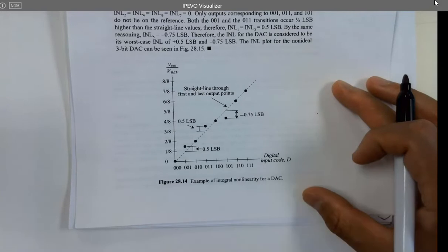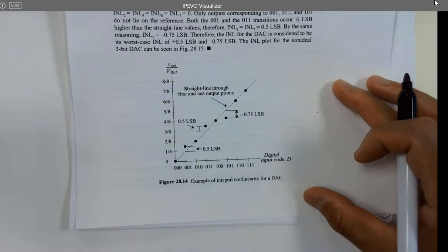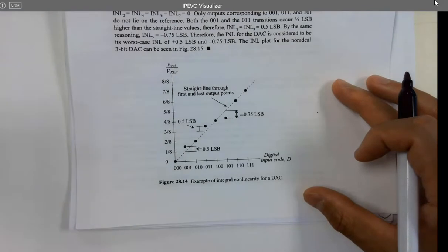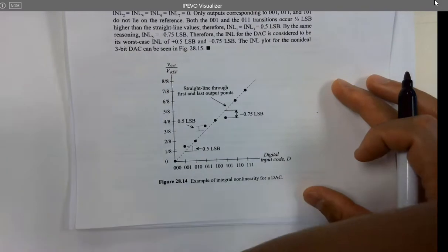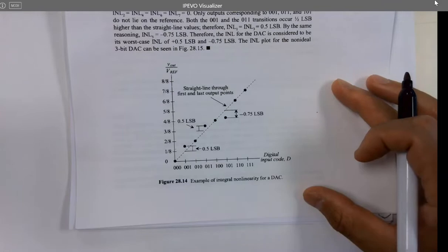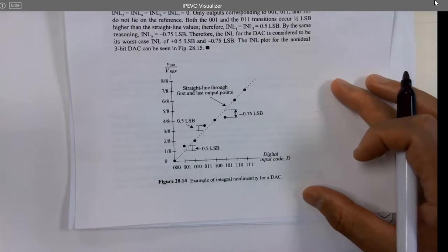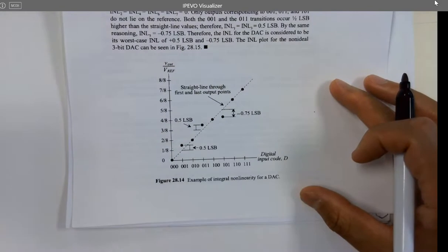So you have one LSB as a digital one. It has a corresponding 1-bit increment in the analog. The actual volts depends on your VREF, right? It's like the temperature or the sensor, the last example I introduced last time. So to resolve 1 millivolt for a DAC, that 1 millivolt can also be called one LSB for the system, for the corresponding analog 1 LSB.